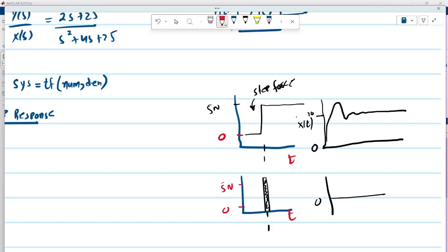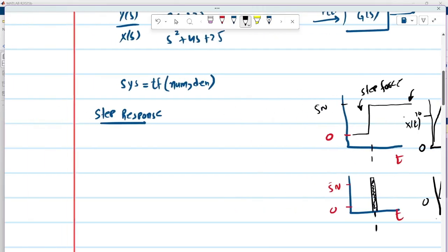For the impulse one, it will be excited for some time, and it will slowly get back to its zero line because the force has been removed. The energy will damp out. But here you are maintaining that force value, so after some time there will be a steady state at a constant magnitude of displacement. Here, in that case, the system returns to its neutral position, or zero position, you can say.